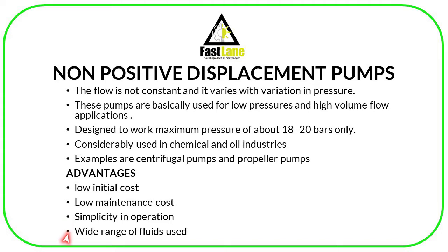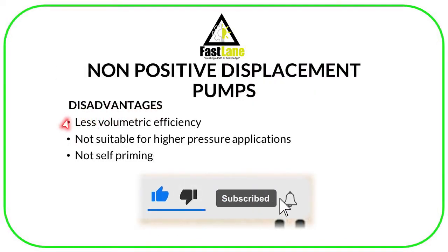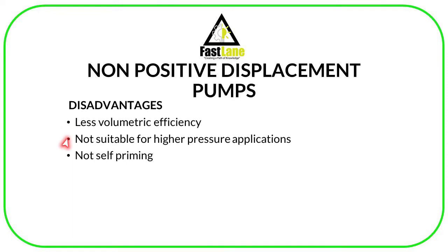Then a wide range of fluids can be used. And then disadvantages: there is less volumetric efficiency, they are not suitable for higher pressure applications, and also such pumps are not self-priming, so they will require a positive suction for smooth operation.